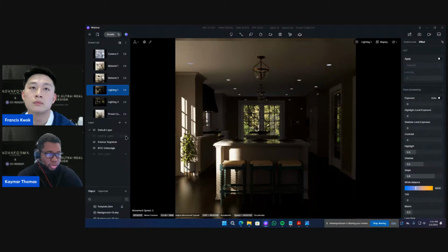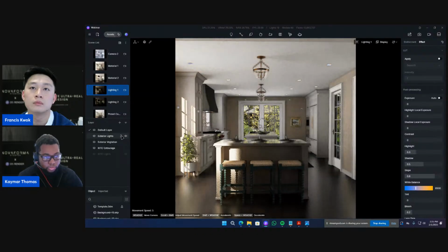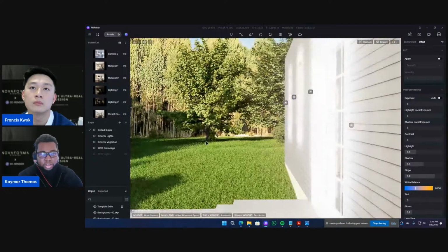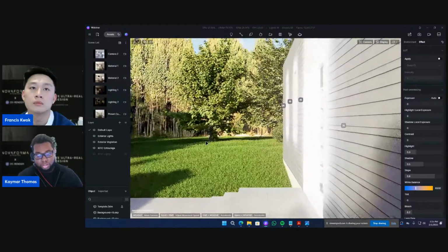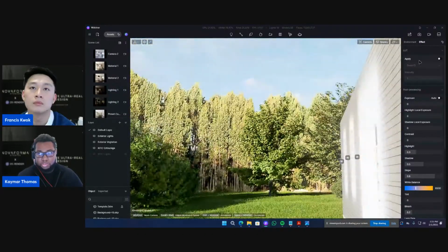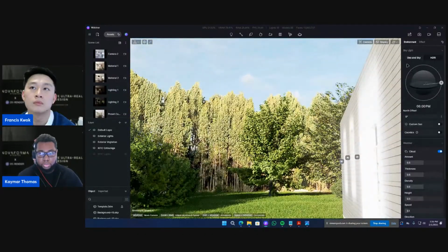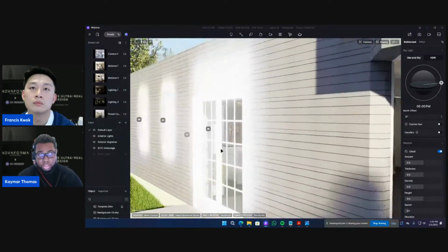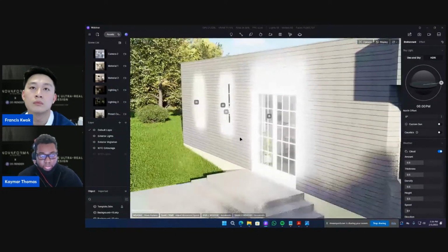So we put the primary lights, which I like to call exterior lights, in their own layer, and we call it exterior lights. So we first turn that on, and to show you how we do exterior lights, exterior lights is broken down into 2, right? We have the sunlight, which is from the scene, which is the geo and sky or the HDR, and then we also have these lights that we create to help that as well.